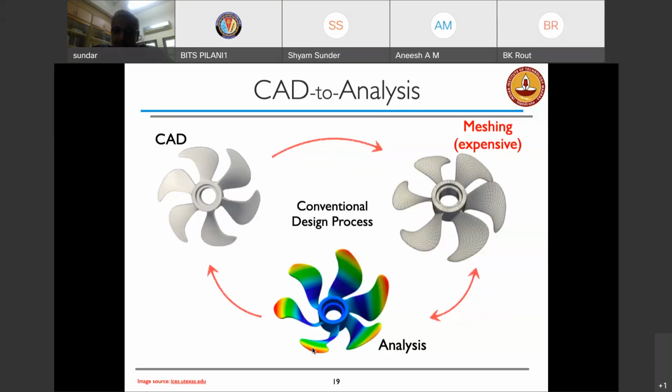But once you have the discretization done for the domain, then we can invoke one of the analysis techniques available to us to compute the necessary information. So it could be the first natural frequency, or the mode shape, or the stresses, strains, the displacements, and things like that.